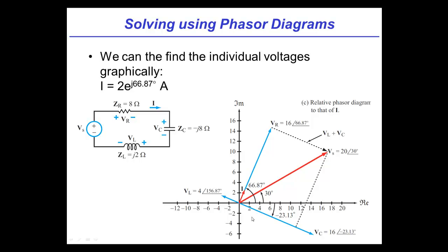Got it. So now this is kind of neat because you see various things here. One is when you have these complex impedances, the current and the source voltage can be out of phase with each other. In fact, they commonly are. And further, if you look at the individual voltages across the individual components, those may have leads or lags with respect to each other as well. That's right. So that's a good point to end.